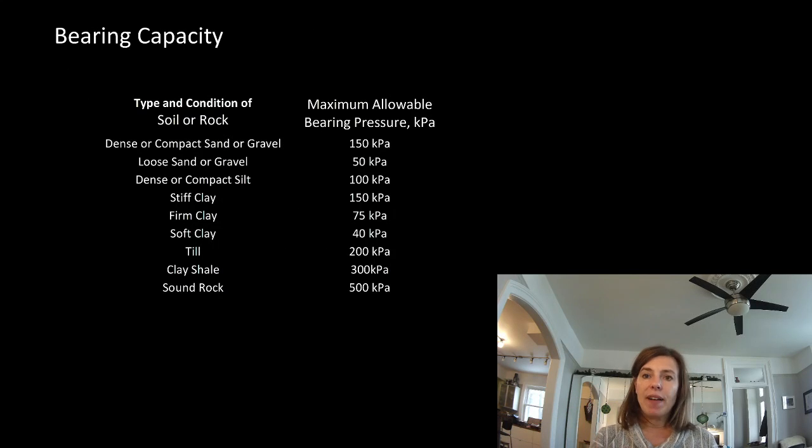As much as they give us the bearing capacity of the soil, base building engineers often don't have that report when we start the design. So we have to make some early guesses to at least be able to start for schematic design and preliminary costing, so the owner even knows if they want to build this thing. We often recommend getting the soils report as early as possible. There's not often that we say, no, you can't do something, but a soils report can say, no, you can't do something. Or it can add a huge expense to a project.